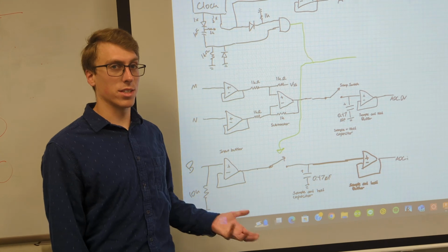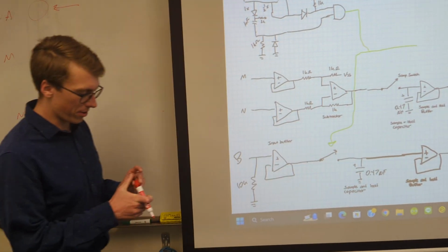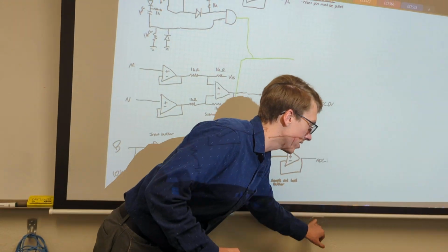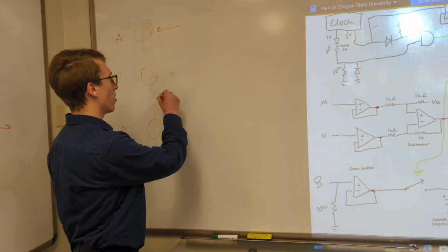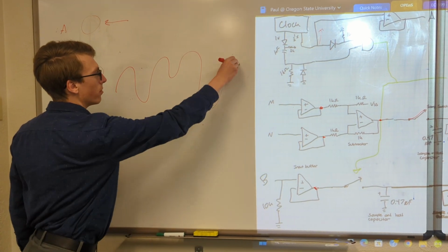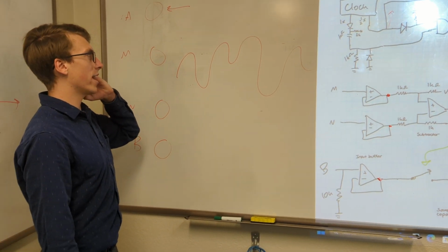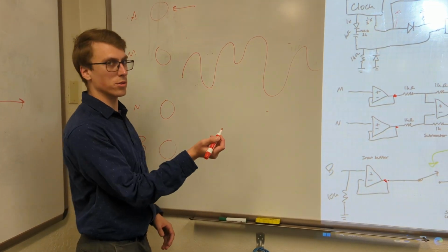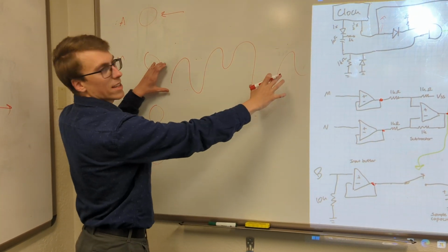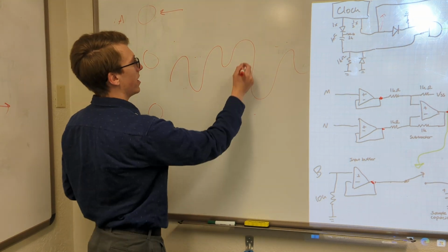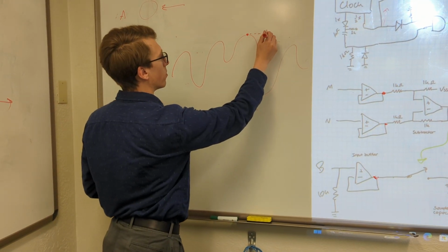Now, the sample and hold part. Suppose we have a transient voltage, say a sine wave or some other arbitrary voltage pattern. I can draw any wave that I want on the screen. The objective of the sample and hold circuit is we want to say, okay, at a certain time, we want to sample what the voltage is, and we want to be able to hold that voltage so we can record it. So let's say this is like the input to an oscilloscope or some other device, and I take a voltage measurement here. And let's say this voltage measurement is like 1.6 volts.